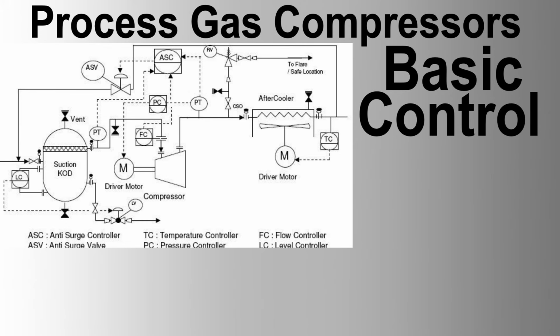Key components and functionality. 1. Low pressure LP and medium pressure MP process gas compressors. Function: these compressors increase the pressure of the gas from the LP and MP stages of the production process. VFD integration: VFDs are used to control the speed of the compressor motors, allowing for precise control of gas flow rates and pressures. Multi-stage compression: the gas may go through several stages of compression, where each stage further increases the gas pressure.